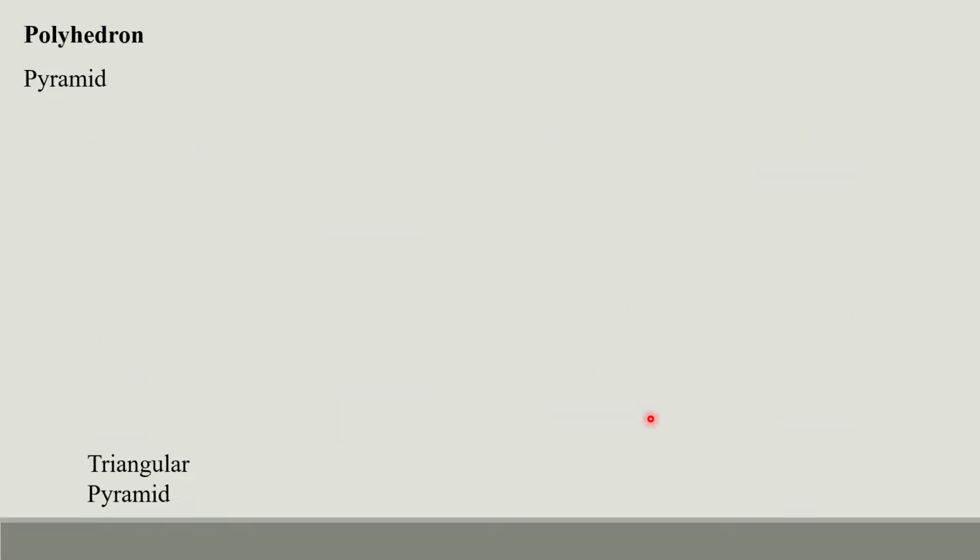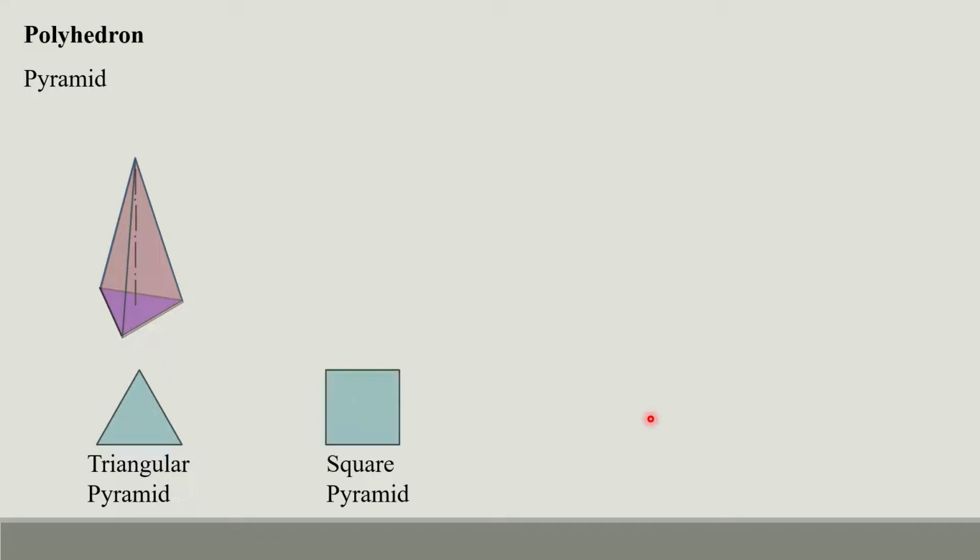If a pyramid is considered, a triangular pyramid has a triangular base similar to the prism, but the only difference is that here you don't have any top surface, you have an apex. So I have three lateral surfaces here also, but the shape is different. First one is this, the second one, and this is the third one, and this is the base. In the case of a square pyramid, we'll have four lateral surfaces, the first one, the second, the third, and the fourth, and this is the base. The axis is shown here, which is clearly visible in a pyramid rather than in prisms. It gets hidden due to the vertical longer edge.